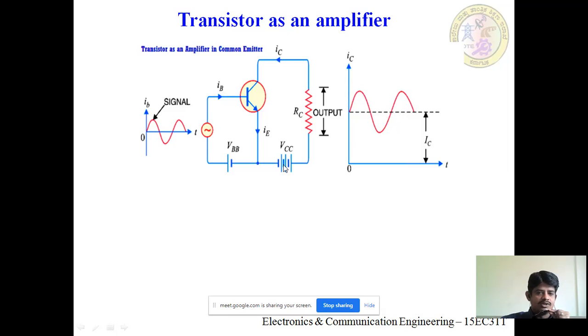Okay, so this DC will set the operating point. Operating point means how the transistor will operate. That operating point is set by the DC without any input signal. So the input signal does not play any role there. We are using only DC to set the transistor. Once the transistor is set to operate as an amplifier, then we apply the signal. That signal is normally in AC form. Remember what signals we have: we have an AC as well as a DC. DC is used to set the transistor to operate in a particular region, and AC is the input signal. So, understood this? Since we have made this forward bias and this reverse bias, it is operating in the active region.